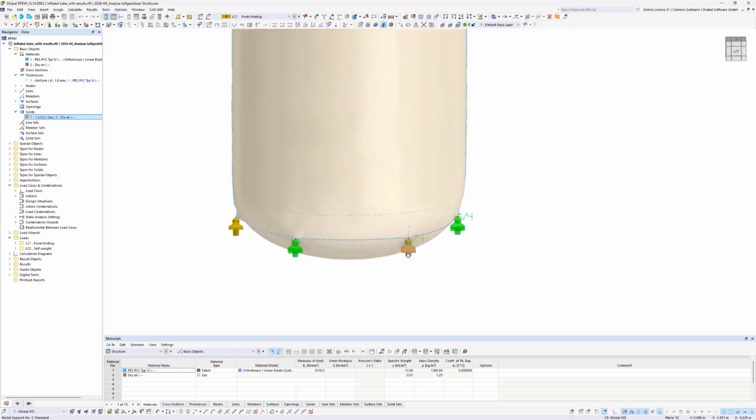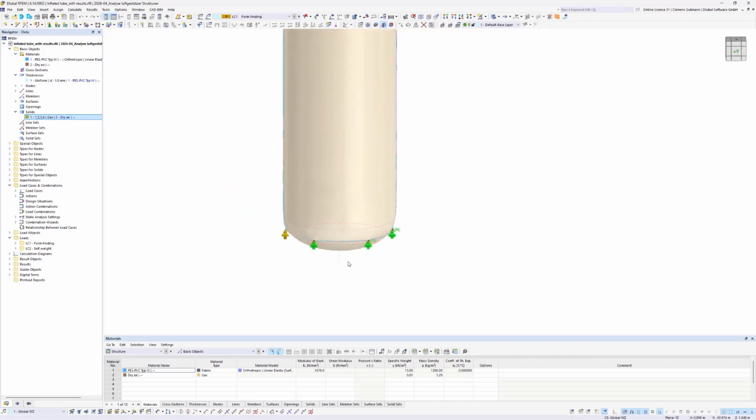There I have a spring. You can also think of a line support maybe. I also recommend trying out the surface support. Maybe it works for your structure, but keep in mind that there might be issues, especially if you try to use the nonlinear behavior of the support. So when the surface lifts up from the ground, that the support is 0.